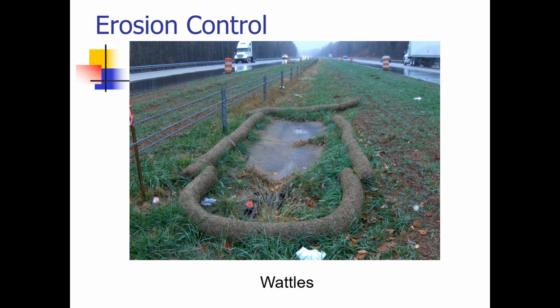And if you look over here at the inlet, that's pretty heavily covered. We need to get that cleaned out, because if the water gets there, it needs to be able to flow properly. We need to get that water away from the roadway as soon as possible, and that's going to slow up the flow. So make sure that that's cleaned out and make sure that it's clean and free of debris as well.